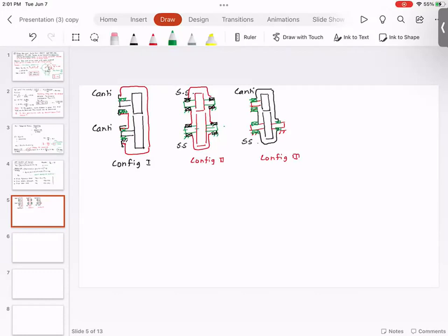And this basically means the pinion shaft will be of bigger diameter. The gear shaft would be of smaller diameter. The bearing designs would be slightly different. And again, there is no right or wrong answer here. You can choose the appropriate configuration that you want to work with and then go from the dimensions.